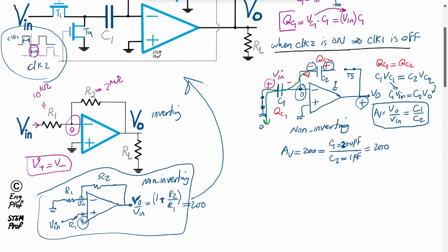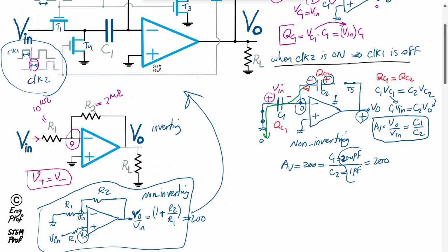So what is the benefit of this? Well, the sizes of the caps, 1 picofarad, or even, if you want to be more realistic, super practical in terms of chip design, let's say 0.1 picofarad. So maybe I just say, sorry, my bad. That 1 picofarad is good enough. Let's keep it 1 picofarad. And for now, let's stick with 200 picofarad, but you can go lower. This one can go to half a picofarad or even lower, depending on what technology node is used for chip design. I'm just trying to give an illustration here. It doesn't mean these are the best choices in terms of numbers.